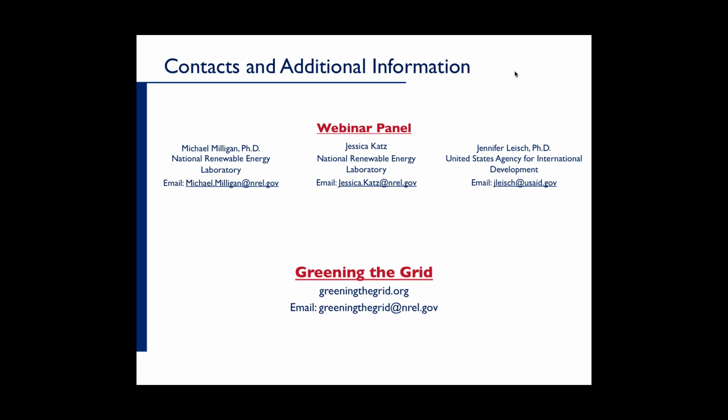The last comment I'd like to make about forecasts is that frequently updating the forecast can be a valuable thing, because as you get closer to real time, the forecast accuracy can improve. But at the same time, there needs to be some sort of an operator action associated with a new forecast. So for example, if somebody says, I can give you a pretty accurate 2-hour ahead forecast, the question becomes, what is the system operator going to be doing 2 hours ahead of real time? And if there's no system operator action that happens 2 hours before real time, that forecast may not be terribly useful.